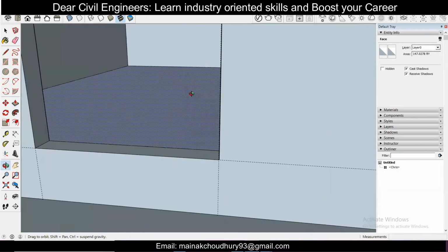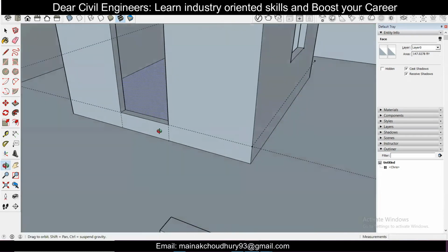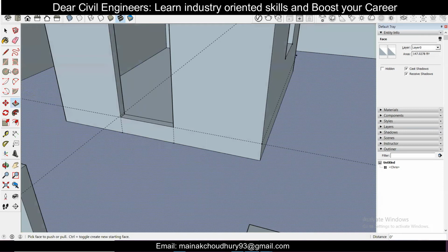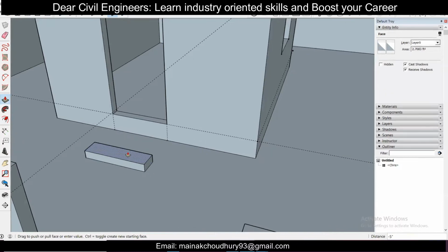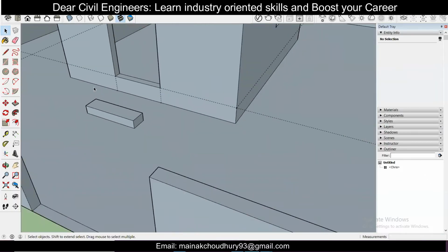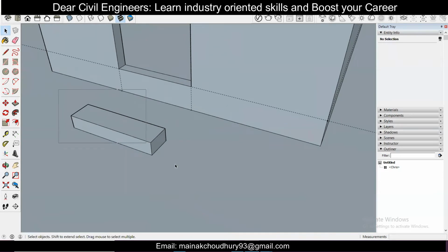Okay. So now let's go here for the staircase. So just make a rectangle here, and let's go with the same size stair, that is 3 feet 3 inches, and comma, that will be a 10-inch tread. We can provide a 10-inch tread, and click on enter. Here let's provide the riser for this staircase. So let's give a riser of 6 inches. Enter.